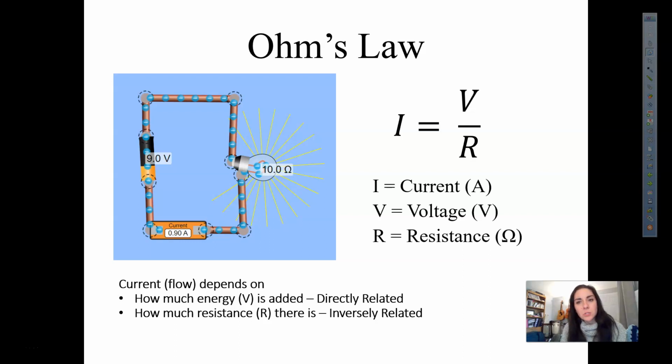Ohm's law is linear. There's no squares or square roots or cubes. If you were to plot this, you can plot it two different ways: current versus voltage or voltage versus current. It doesn't matter. Either way would give you a linear line, which represents the resistance of the circuit. Things that follow Ohm's law have a linear relationship or constant resistance. Resistors follow Ohm's law, but light bulbs do not, because over time light bulbs get hot, which changes the resistance. So that's why you get a curved motion with that. I'll let the lab talk more about the resistance in Ohm's law.